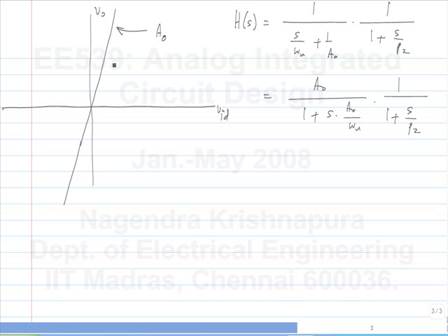So what non-idealities may we have here? Saturation. So what does it mean? The output will be fixed at some value. Beyond that, the voltage will not increase indefinitely as you increase the input voltage. That is, the range of output voltage is limited to some value. So in reality, on both sides, it will be limited.